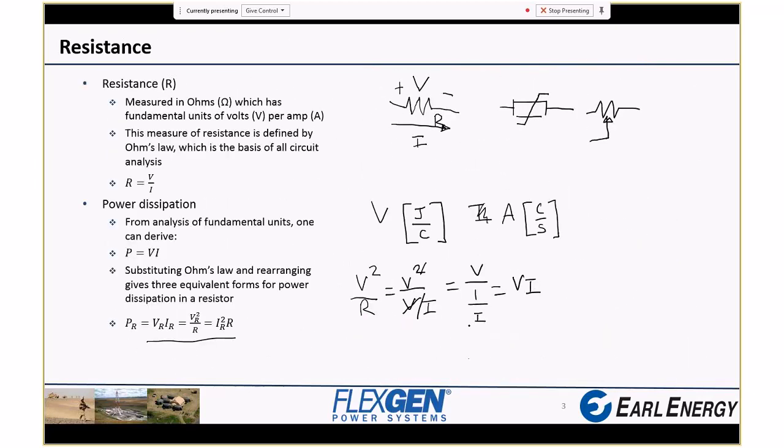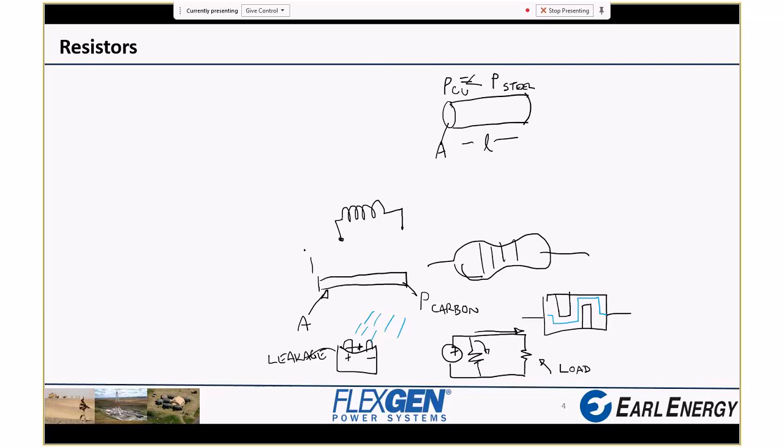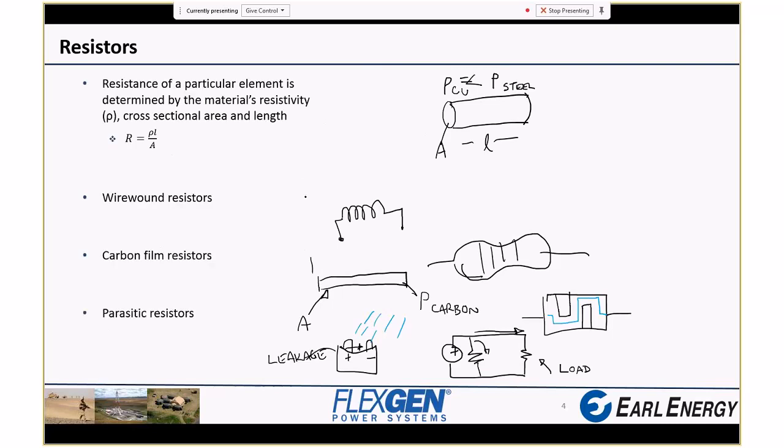wire-wound resistors. I talked about them back here. You take a piece of wire, spin it up in a coil to look like a resistor, and surprise, you got some inductance, even though you didn't mean for it to happen. And these are all things that once you understand how they can happen in a way you didn't intend, you can counteract them. Wire-wound resistors in particular,